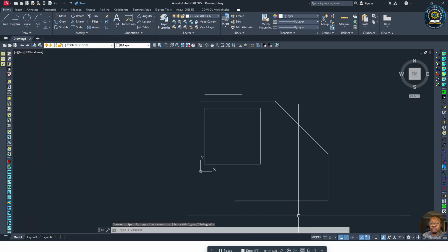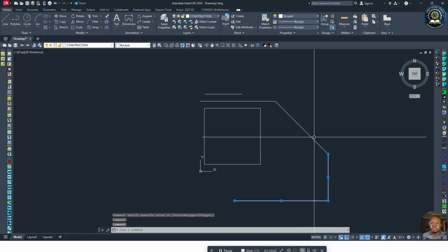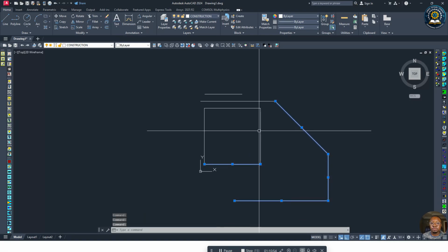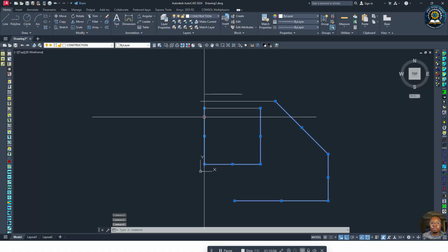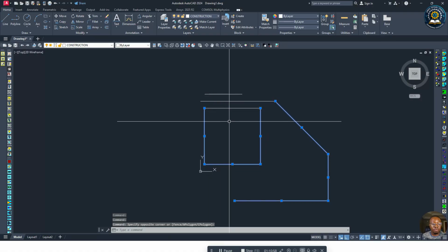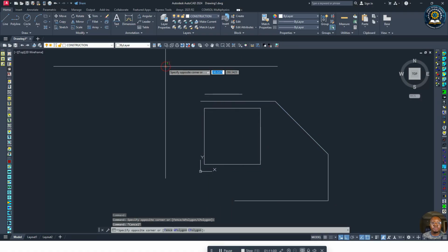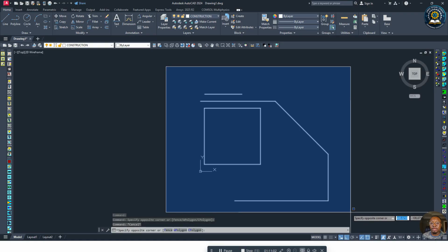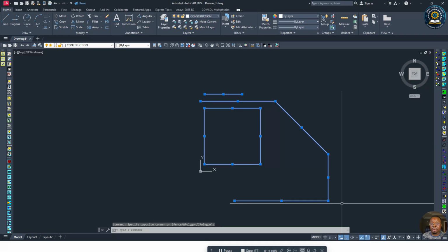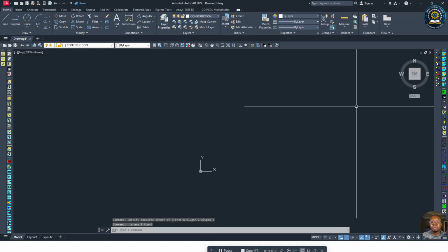We can delete the line tool drawing by selecting the various line segments one by one, or you can click on this space, move the cursor over the whole line or the number of lines that we've drawn, click on the end, the other end, and then press the delete key to delete the lines.